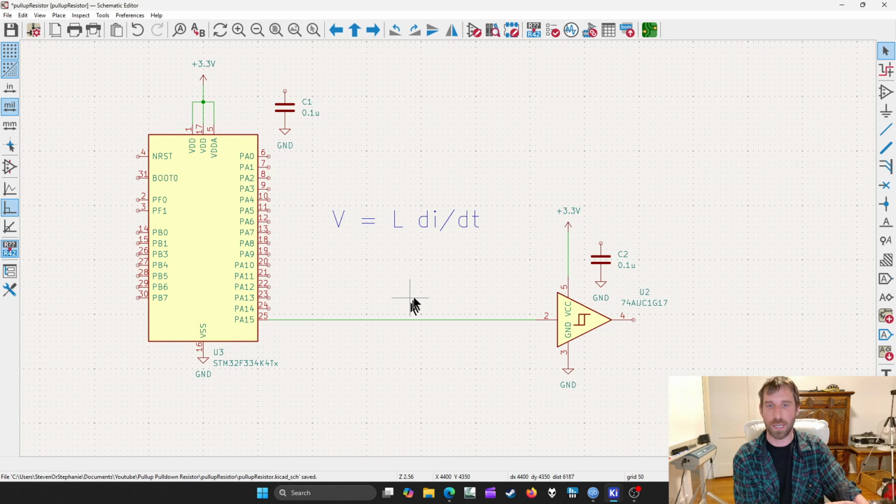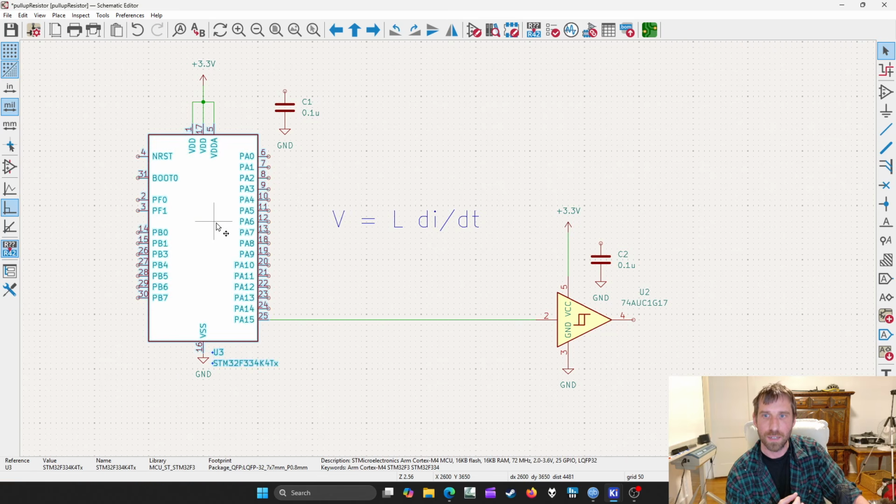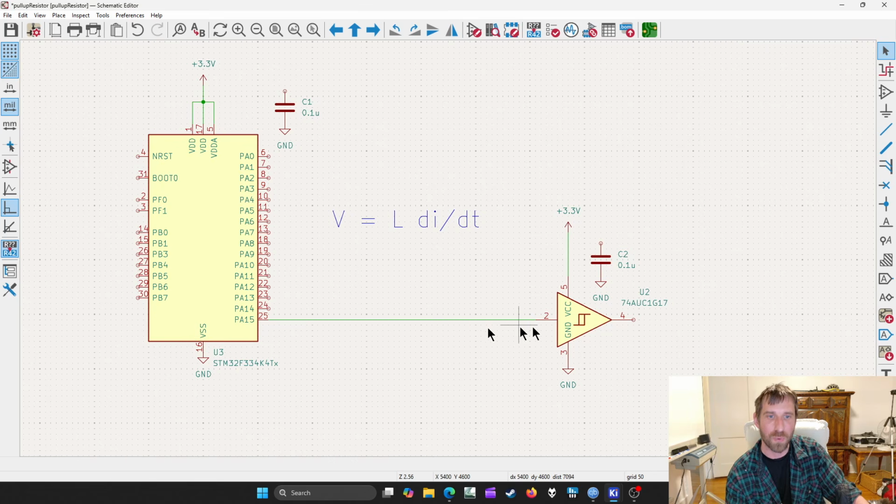Let's say this was pretty much all you had on the circuit. So you've got this thing, a trace, which has low L, and then you have high impedance here. So your di/dt is going to be really, really low. And we're going to assume this output has the same thing. It's going to be a trace, low L, whatever it's going to, di/dt.